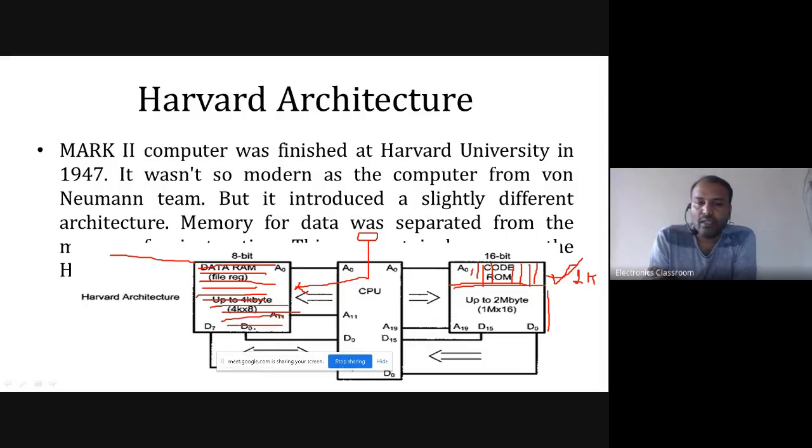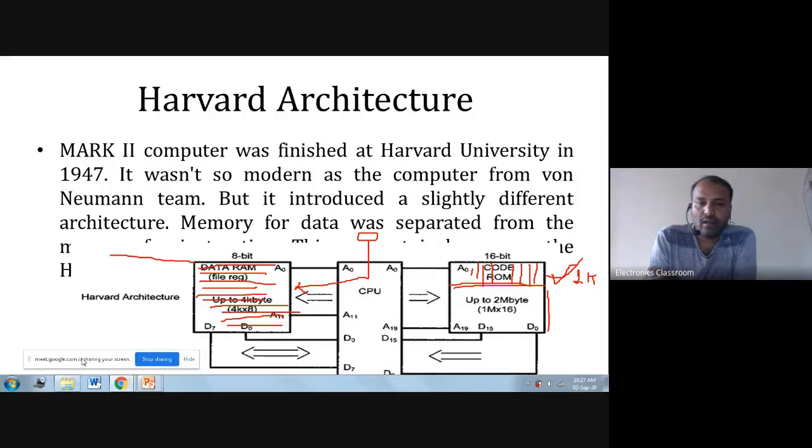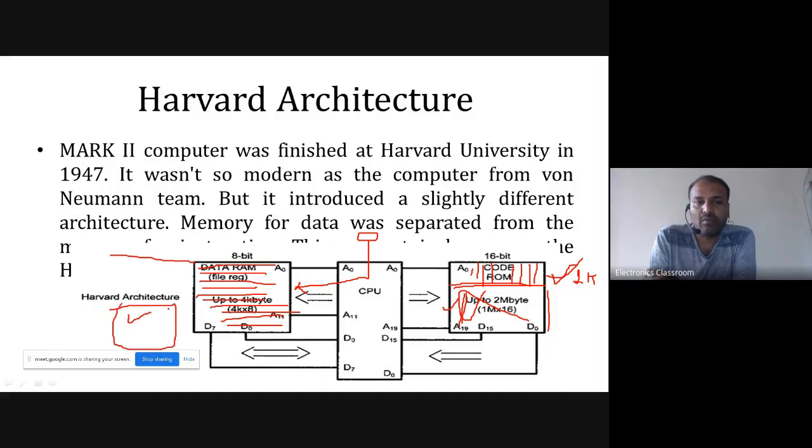After getting full, this microcontroller cannot save the next temperature values to the unused bits of code memory. Since your data memory is full, it cannot go to code memory and store your temperature. This memory will be left as it is. To overcome this problem, you need to interface external memory for storing data.